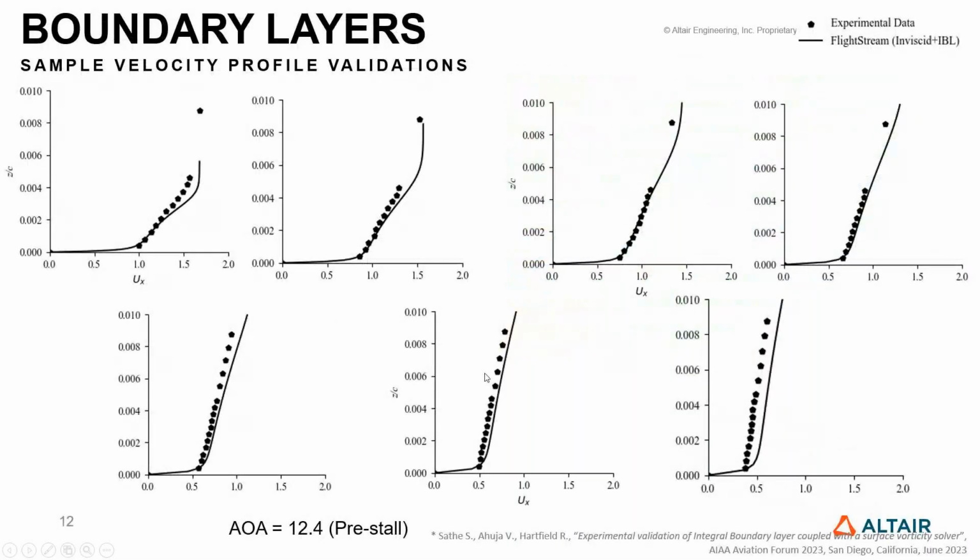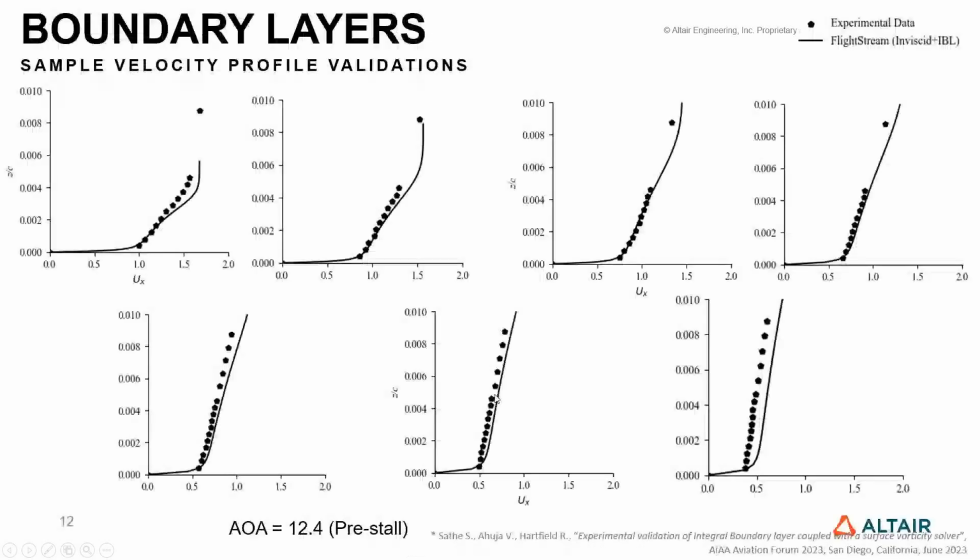Here the boundary layer profile is pretty advanced, with a similar log-type scale boundary layer like you expect from RANS tools. You can see the nice correlation with various angles of attack, and we can see the drag in a momentum deficit simulation similar to regular CFD.